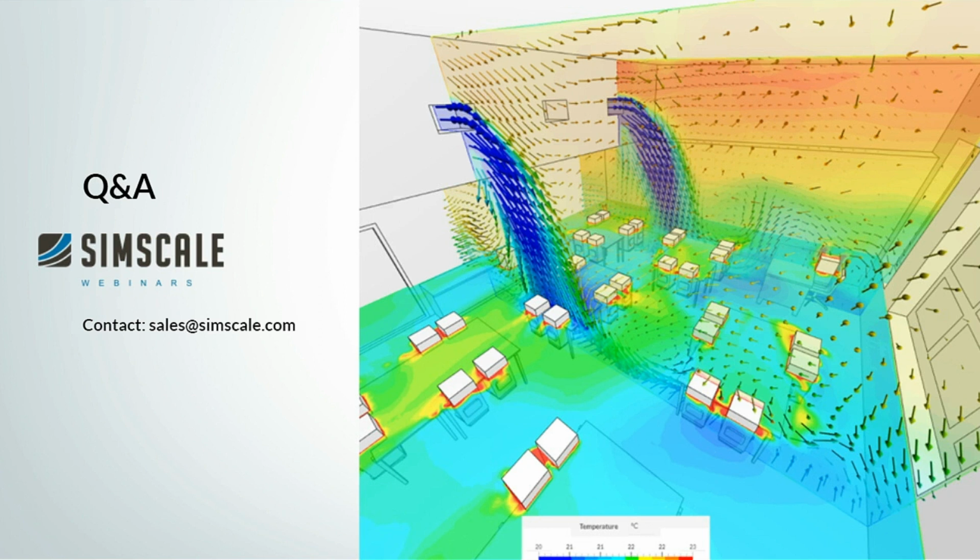Okay, there are several questions about importing the geometry and how we can actually make use of changes in the geometry. So as I mentioned in the live demonstration, if you have a CAD tool which can actually allow you to provide a named tag for all these surfaces, then you can tag them according to your inputs and then bring it into SimScale, which will be again recognized for your boundary condition setup. And this will help a lot if you have slight changes in your geometry, but you have to run multiple simulations for different configurations.